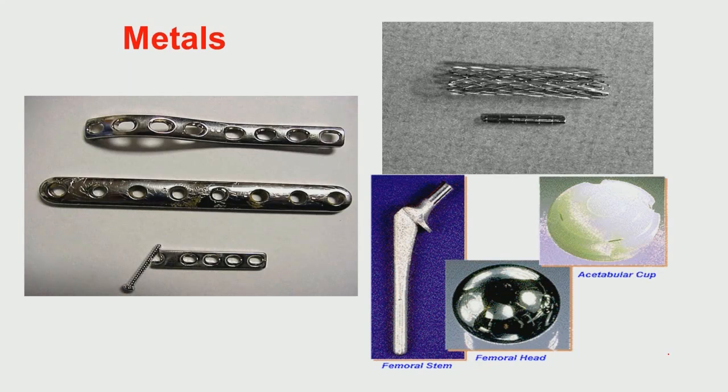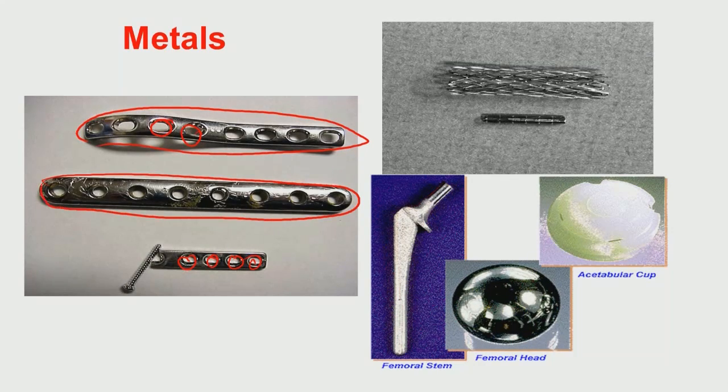So, these are different examples of metallic plates which are used in these applications. You can see these holes right here. These holes mean it has to be used by drilling. Now, if you imagine using this long plate made of some ceramic, the moment you try to make a hole into the ceramic plate, this entire plate will simply fracture into two pieces, simply because it will not be able to sustain the drilling induced stresses, and it causes significant cracking and fracture.